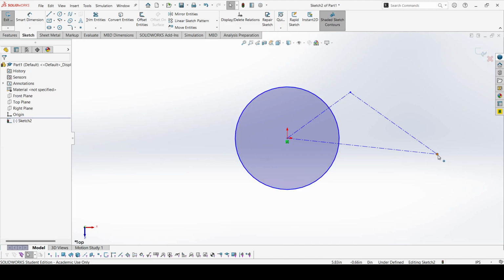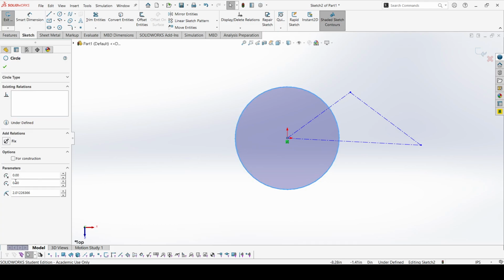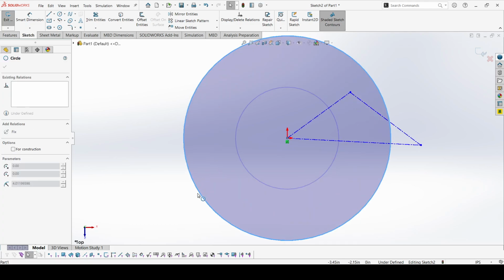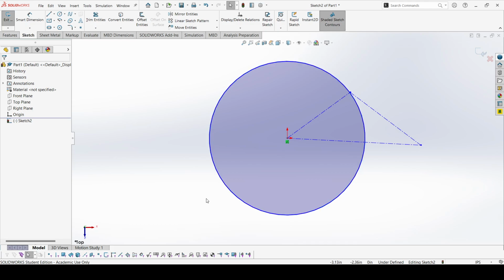Now, you'll notice everything's blue. This isn't fun. Blue means things are undefined. Undefined isn't good. Now, I know you look at this and think, oh, let me just set the radius to, let's say, 2 inches. You think, oh yeah, that's fine, it works perfectly. No, it's still moving, it's still undefined.